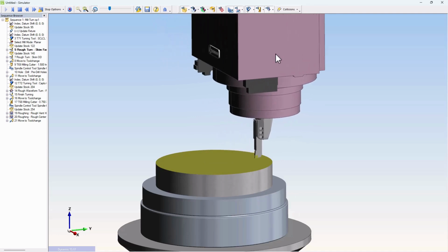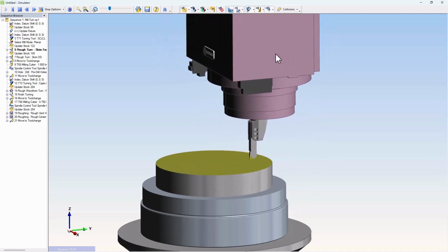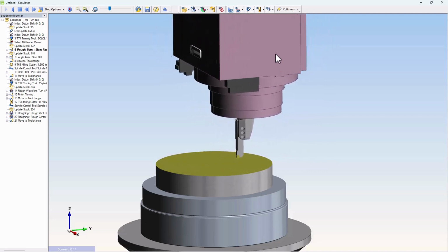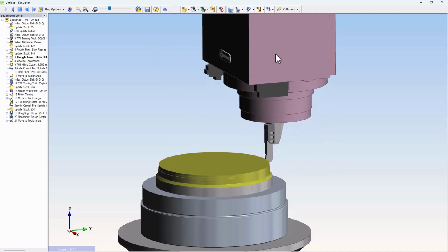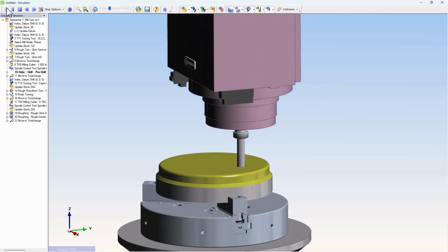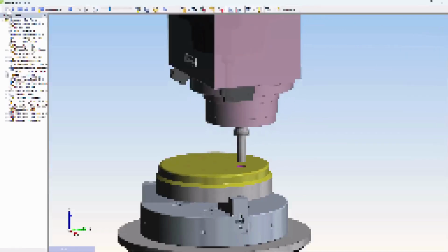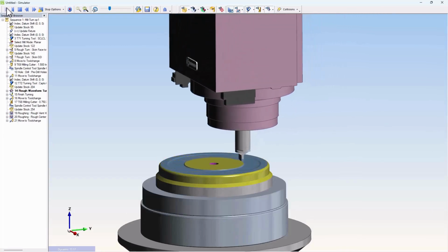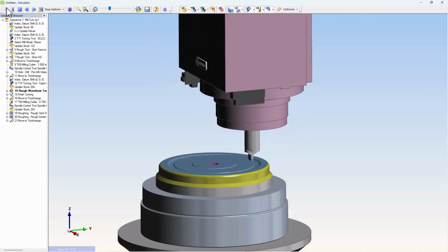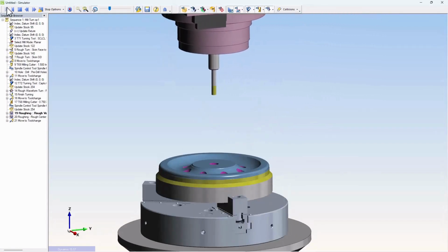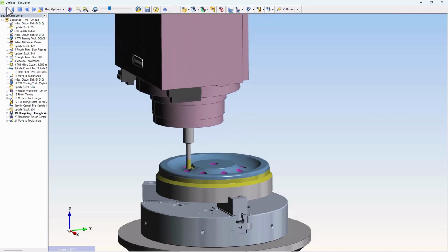Now this is a large diameter part, 19-inch diameter, in unalloyed steel for a railway wheel. So there's quite a bit of work the tool's doing, then it does some turning. After that tool's complete, a large insert drill is brought up to pre-drill some opening holes that will be used for roughing later. Then we're switching back to turning mode using a full round tool and taking advantage of EDGECAM's rough waveform turning cycle to remove material with that tool from the hub area, and then bringing in a milling